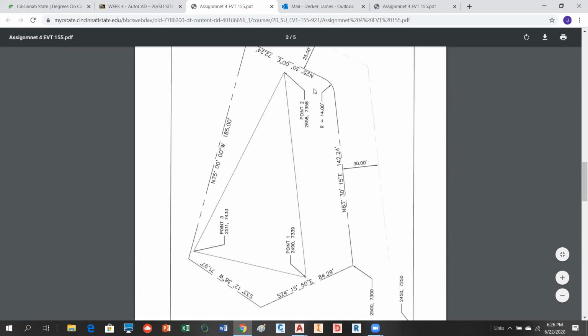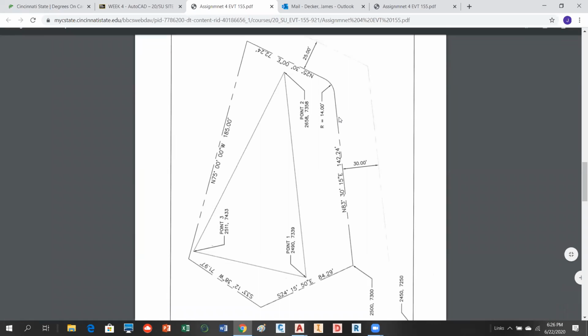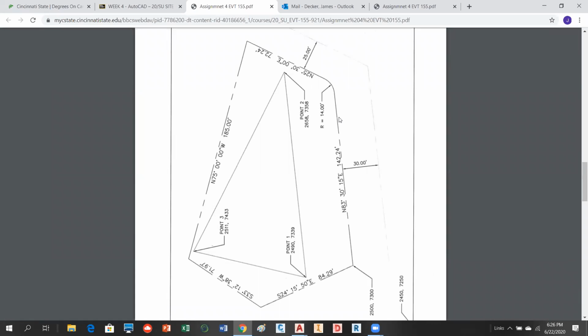So how are we going to put this arc in here? Anybody tell me? The 2 endpoints of the line and then the radius at 14. You could. Anybody want to suggest a better way? That could work, Craig. You can use, oh, fillet. Yes, fillet. You want to use the fillet.